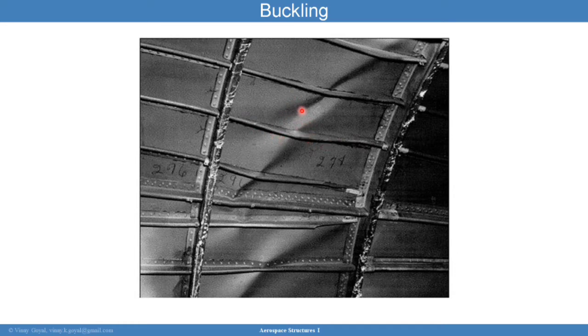Usually, the skin takes the shear loading, while the stringers take bending moment and other loads that have to do with axial loads. An aircraft is subject, and you're going to see that later, aircraft are subject to torsion, bending moment, shear loads. And so the shear loading in this case caused the skins to fail in shear, or buckle in shear, may I say. And sometimes that starts with the stringer also weakening. But those events can occur and need to be analyzed for.